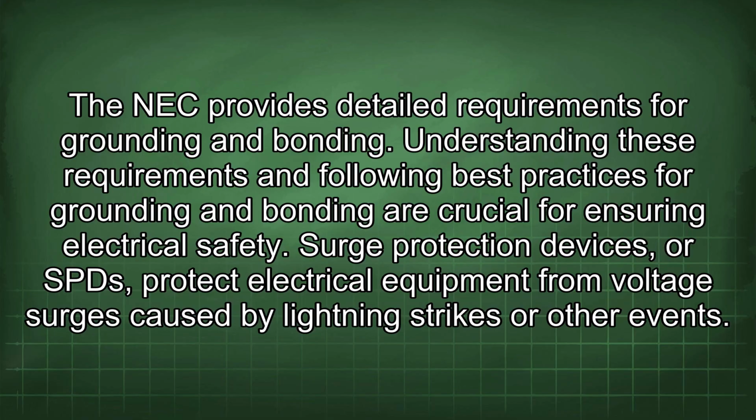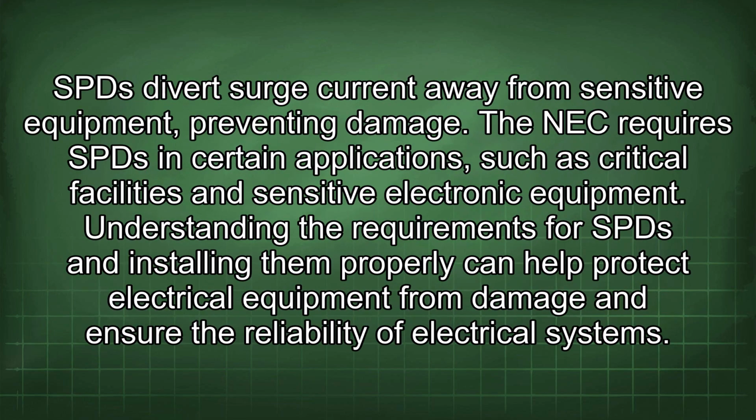Surge protection devices, or SPDs, protect electrical equipment from voltage surges caused by lightning strikes or other events. An SPD diverts surge current away from sensitive equipment, preventing damage. The NEC requires SPDs in certain applications, such as critical facilities and sensitive electronic equipment.